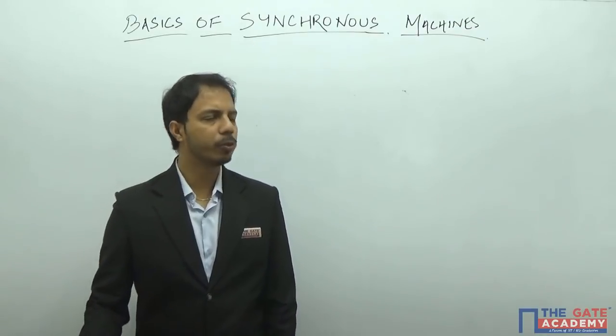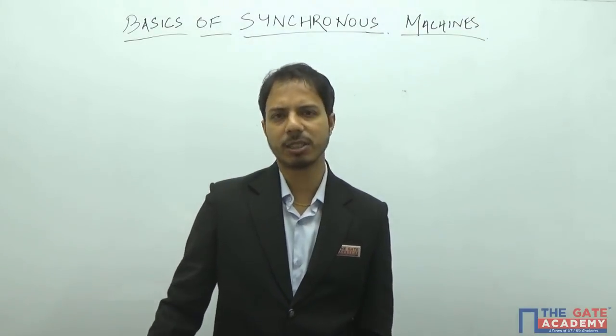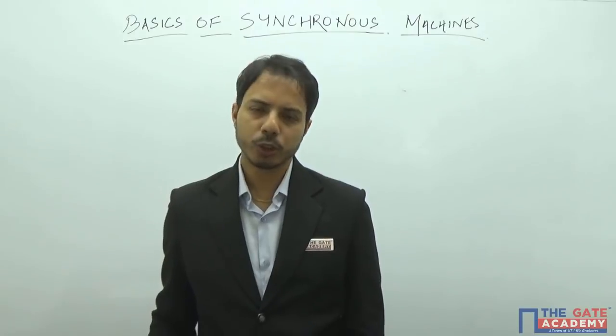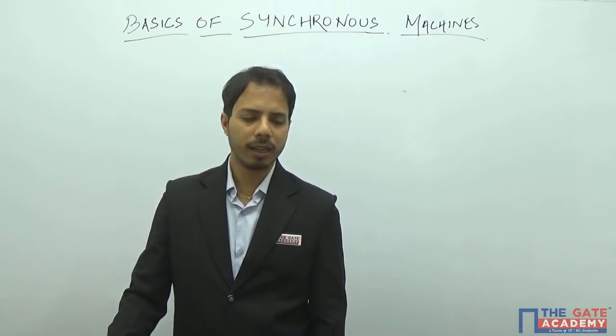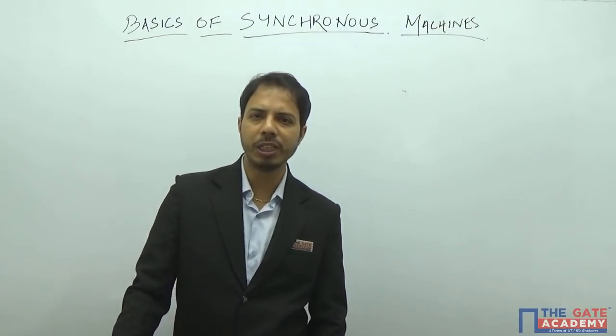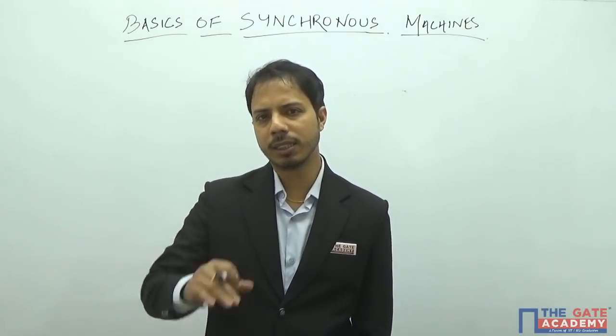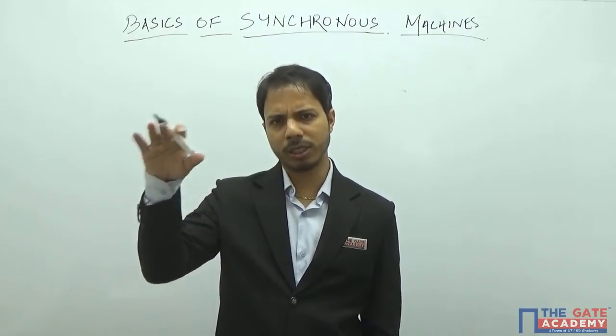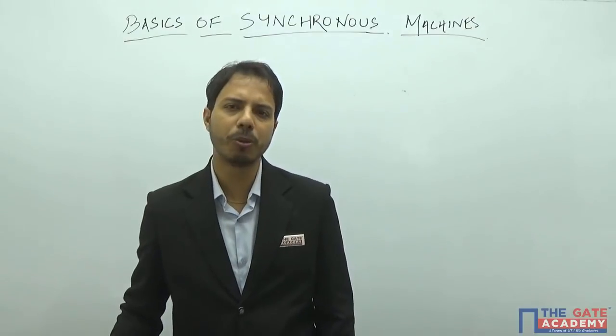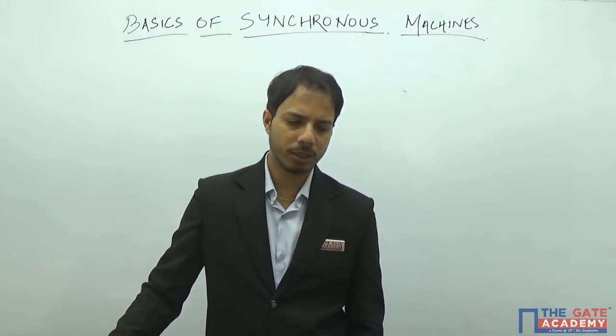In this particular case, we will have a three-phase supply and three-phase winding. If we have these two basic arrangements, we will have a field which will rotate in the air gap, the circular structure which we produce in the windings in the stator.